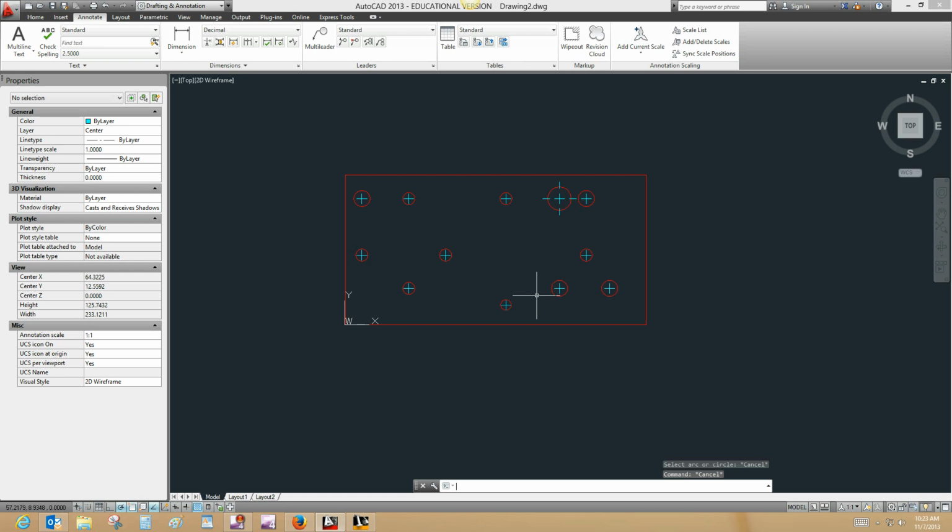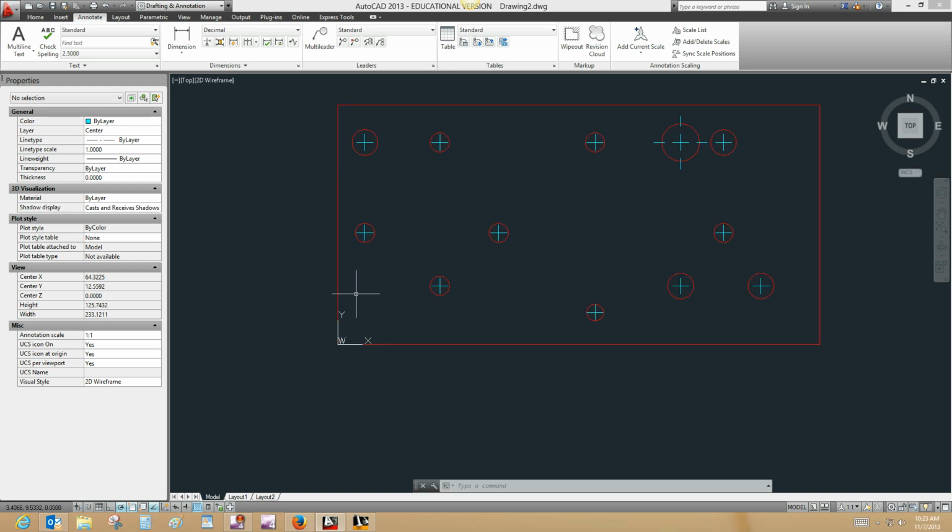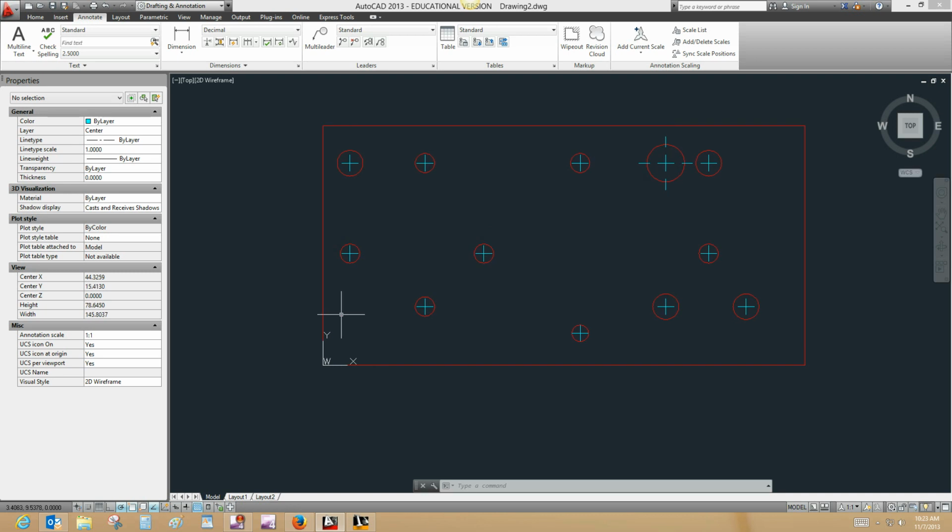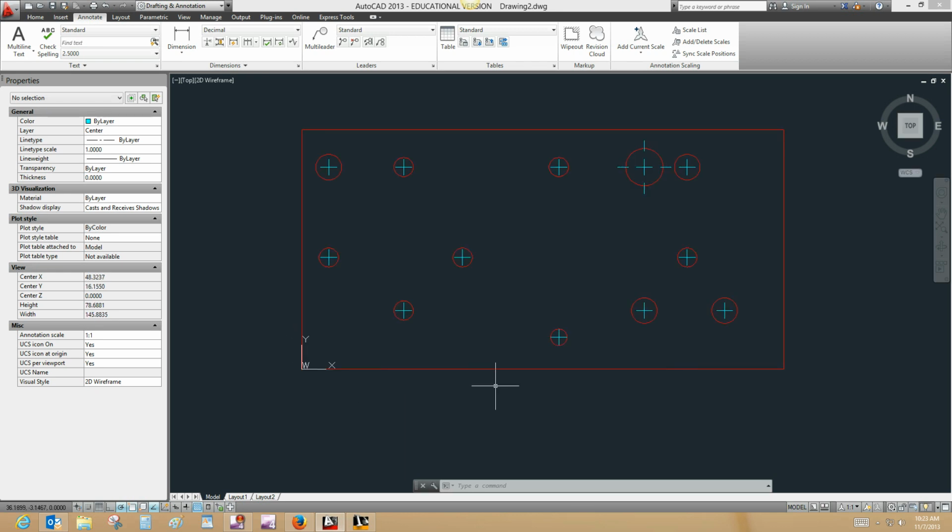Now we need to dimension this object. We're going to use something called ordinate dimensioning. And this is why we created the first point of the rectangle at absolute coordinate 0, 0, because that's our datum. All the other values, just like as shown in the figure in the book, are based off of the origin being located here. And for this tool to work in AutoCAD, it works off of the current origin. So rather than redefining the origin, which you'll learn about later, I just used the current origin, and we'll be able to assign these values very easily because of that.